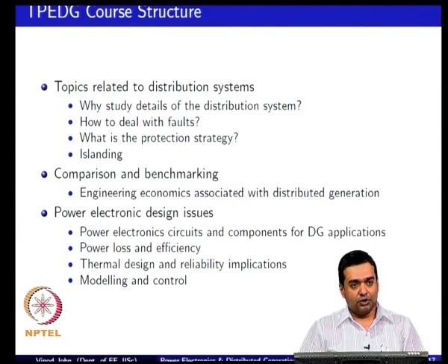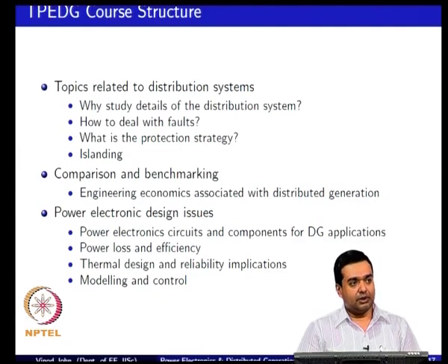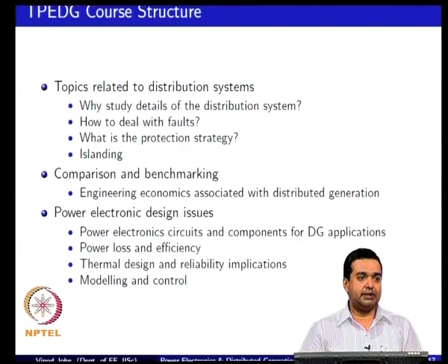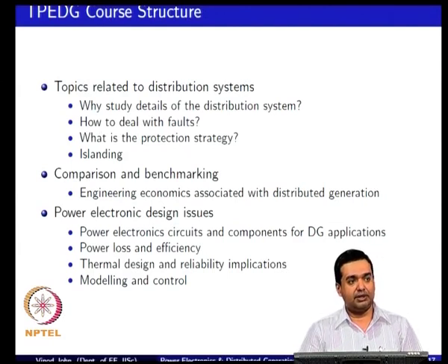So, in a practical circuit you will have losses, and there are implications of loss. One is you lose the generated power that you are generating in your generation source, and you have poor efficiency, that is one impact. The second impact typically is you have more loss, it means that you need more thermal management and your components can get hot, which can have reliability implications.